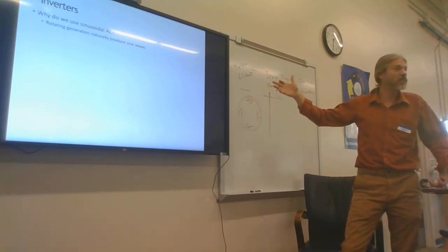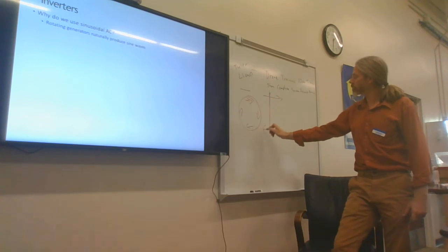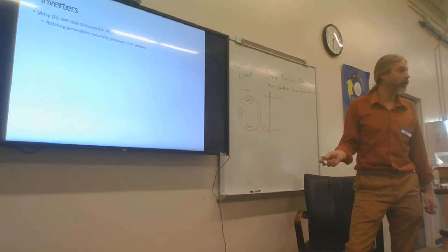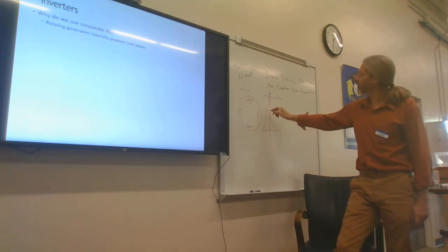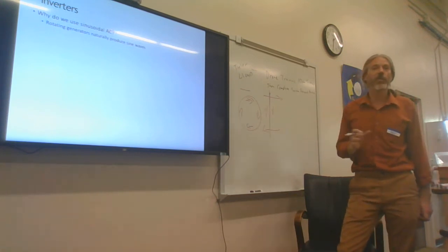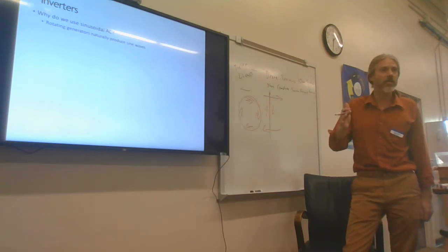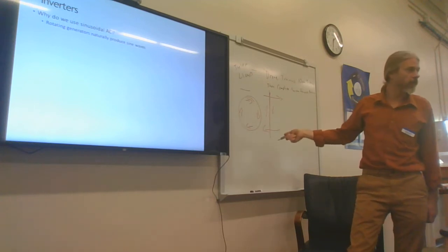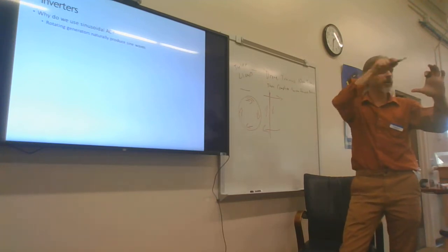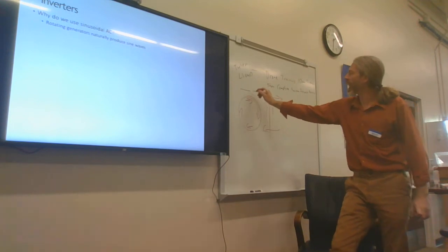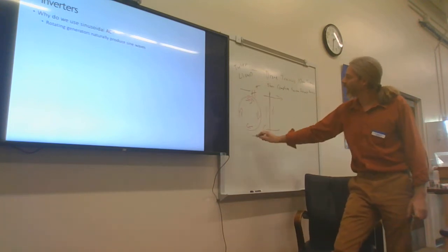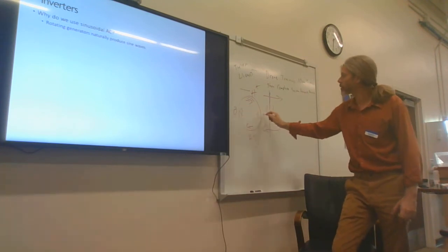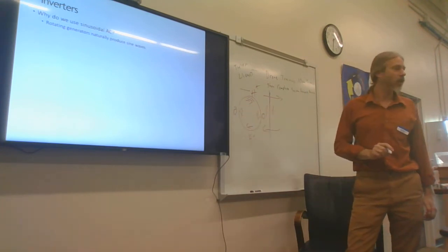When my magnet's moving this direction, it's cutting the wire at the maximum angle, perpendicular. Therefore, it's creating a maximum amount of voltage. Whenever I'm going this direction, it's the opposite, so now I have negative maximum voltage. Whenever my magnets are moving in this way and this way, they aren't creating any voltage whatsoever because their magnetic lines are not perpendicularly intersecting my conductor. Does that make sense? As I go around and around, I have points of high positive voltage, points of high negative voltage, and 2 points with 0 voltage whatsoever.